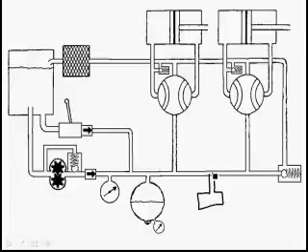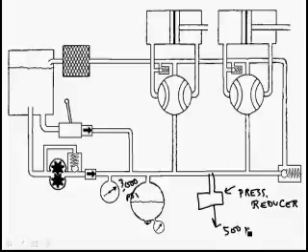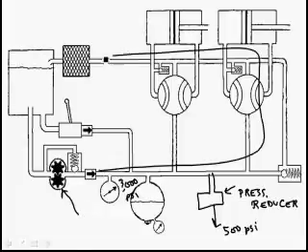So you could put a pressure reducer in here. And then the output, even though the system might be 3,000 PSI, the output might be 500 PSI. That way you still only need pumps on the aircraft that run at 3,000 PSI, which run most everything else on the aircraft, and you don't have to bolt a separate pump to the engine. You can just have a pressure reducer, and we're not going to go into how it works. Hey, we're pilots. You might run things like literally hydraulic-powered windshield wipers, something that doesn't need 3,000 PSI.